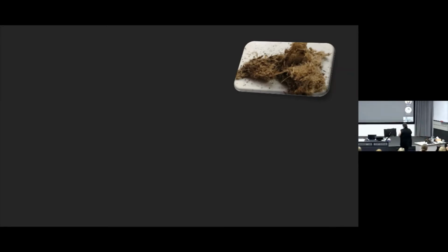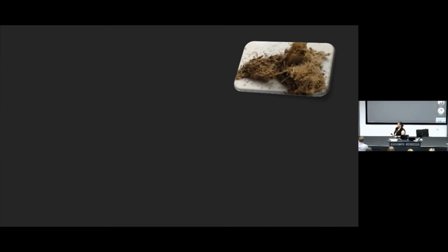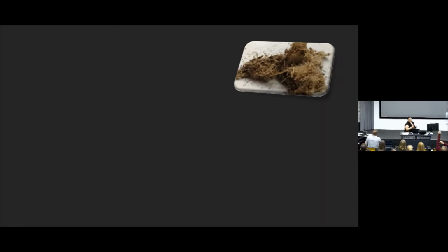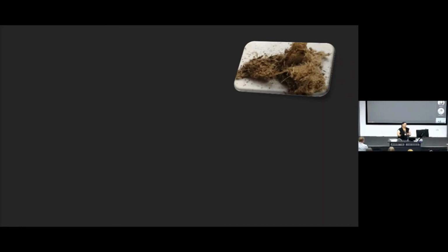It's basically the strength of the bonding material that matters. And the percentage of asbestos in the material matters. And if you've got a high percentage of asbestos or not as good a bonding material in the original manufactured product, by now when it's reached the end of its useful life, it's more likely to be friable. Asbestos cement does tend to retain its integrity, so that's a relatively good thing in the sense that it's probably the most common asbestos contaminant in soil that we have.